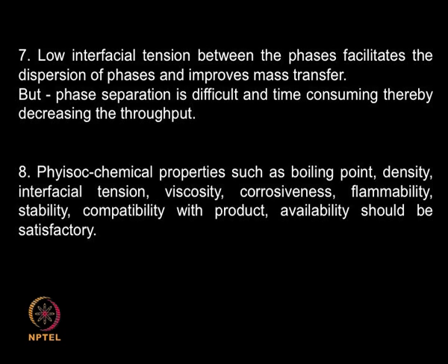For example, it should not be corrosive to the material of construction of your extractor. It should not be flammable, that means you should not use solvents which are highly flammable or have a very low boiling point, because a lot of solvent will vaporize during handling and you will be losing solvent as vapor, and also you will have a possible explosion or flammable hazard if the solvent goes into the vapor phase.